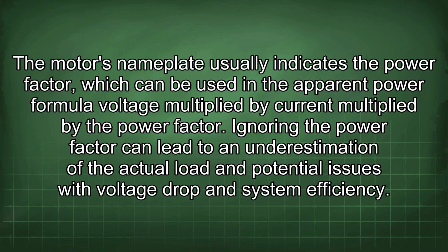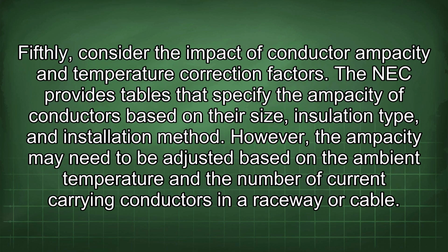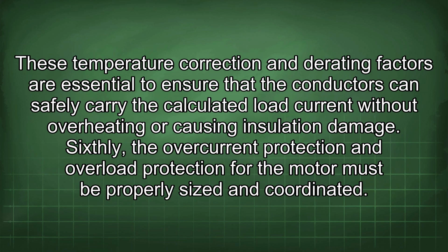system efficiency. Fifthly, consider the impact of conductor ampacity and temperature correction factors. The NEC provides tables that specify the ampacity of conductors based on their size, insulation type, and installation method. However, the ampacity may need to be adjusted based on the ambient temperature and the number of current-carrying conductors in a raceway or cable. These temperature correction and derating factors are essential to ensure that the conductors can safely carry the calculated load current without overheating or causing insulation damage.